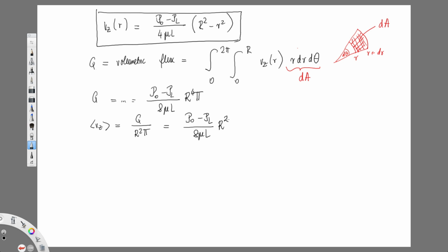Now that I started specializing it, I expressed my tau rz, and that most general form before I actually applied any boundary conditions is again good, maybe plus minus that modification of the outside body force, for any fluid. I still didn't say that it's a Newtonian fluid.